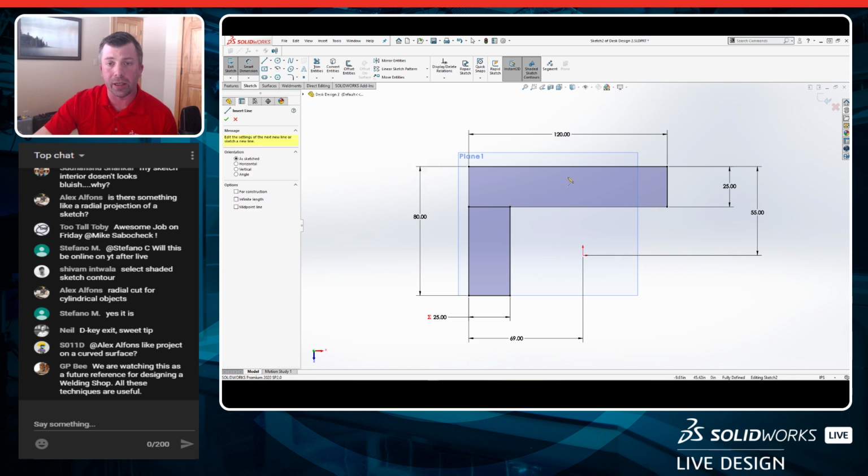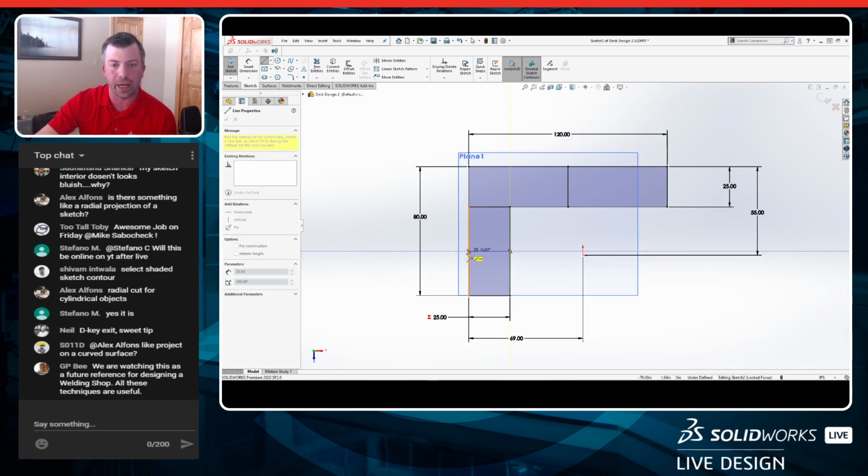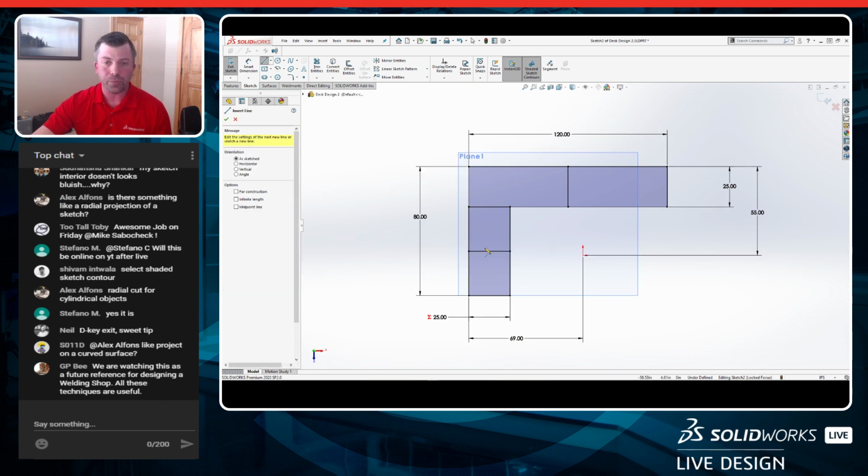What I want to do is add in a couple cross members because this thing is pretty long, 10 feet. And so I'm going to give a center line there. And I think back in, what was it, 2017, we can now inference the center point of a sketch, which is really handy. So I'm going to go ahead and just create 2 center lines there. And then this probably smaller box on the side, I think is fine.